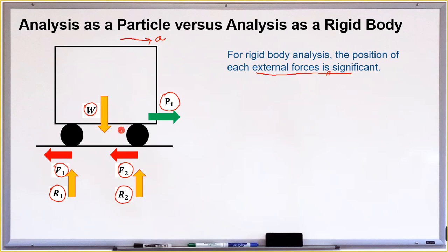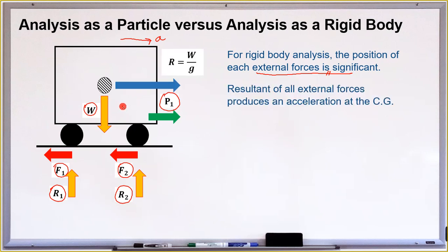Now, since this rigid body is moving, of course, it accelerates. So therefore, we need to find the resultant of all these forces. We sum up these forces: the frictional force, the weight, if it has a component, but obviously it doesn't have a component with respect to the horizontal because the weight always acts vertically in this setup.